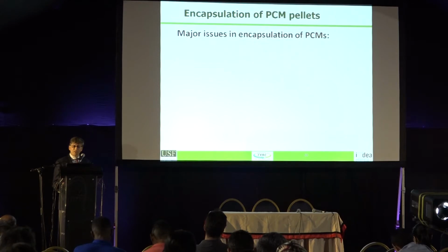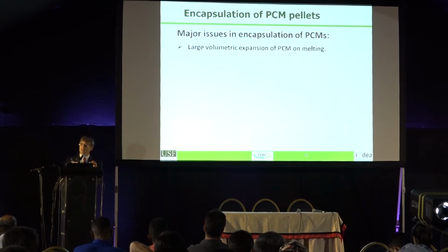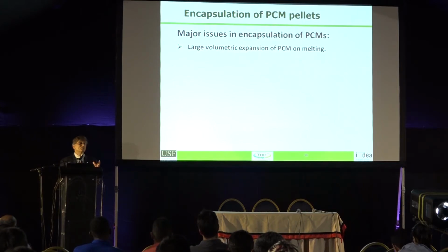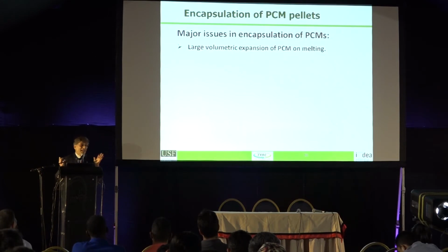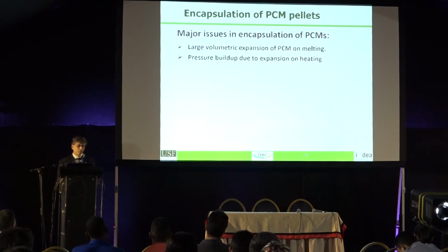But to do that, there are some major issues. And one issue is that when these salts melt, they expand. The expansion can be as much as 30 to 40%. So if you have a hard shell of a capsule and your salt starts to melt, unless you provide space for melting, that capsule is going to break. So you need to find a method which will allow that expansion to take place. Okay. So if you don't do that, pressure will build up.